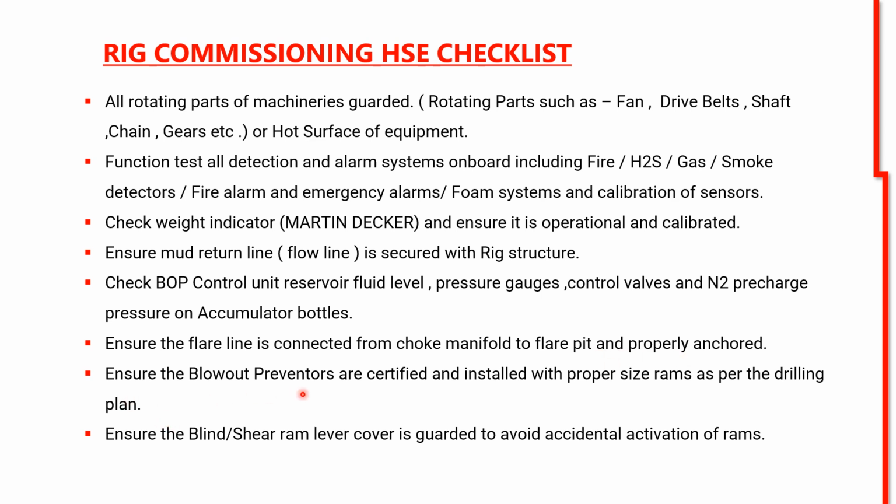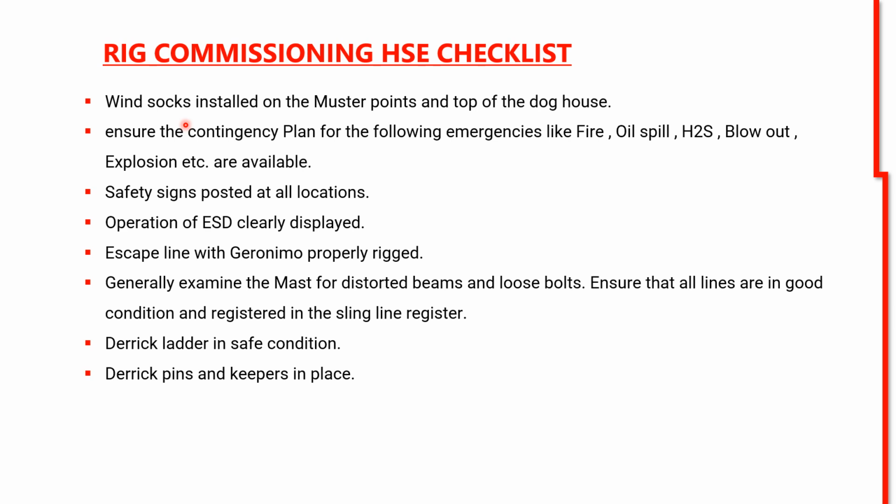Ensure the blowout preventers are certified and installed with the proper size rams as per the drilling plan. Ensure the blind shear ram lever cover is guarded to avoid accidental activation of rams. Windsocks installed on the muster points and top of the doghouse.